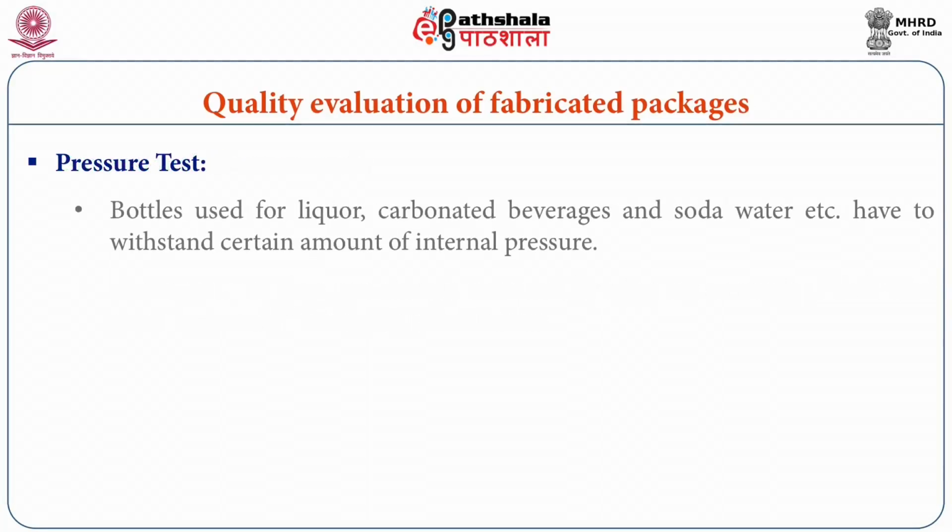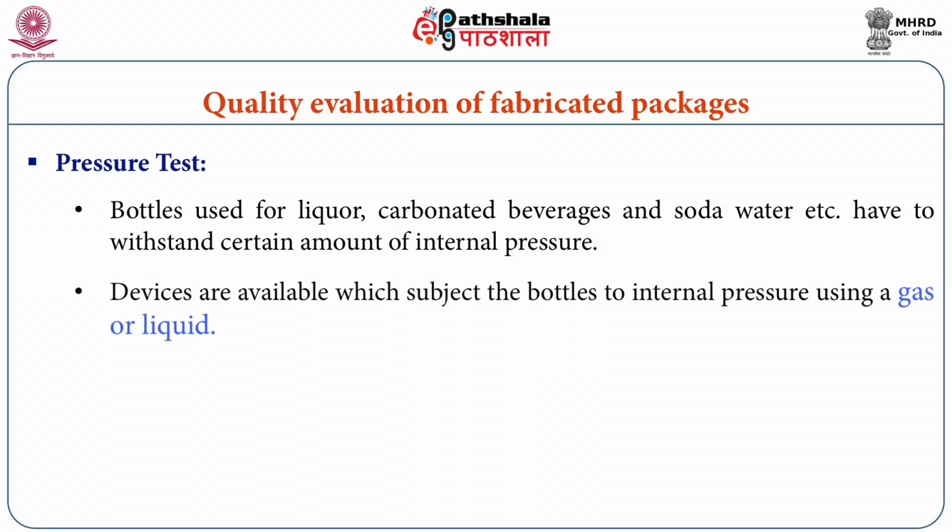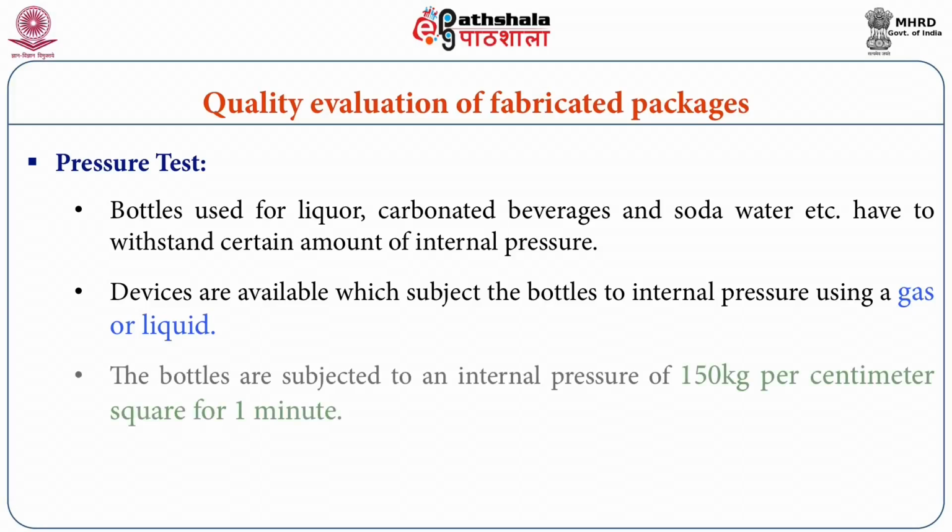Pressure test. The bottles used for liquor, carbonated beverages and soda water etc. have to withstand a certain amount of internal pressure. Devices are available which subject the bottle to internal pressure using a gas or liquid. The bottles are subjected to an internal pressure of 150 kg per centimeter square for 1 minute.